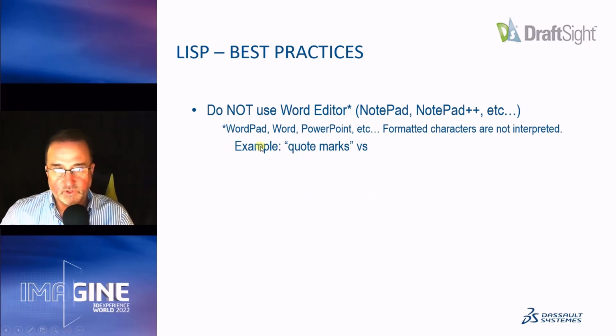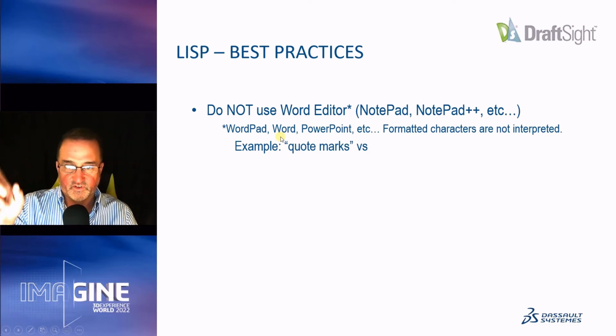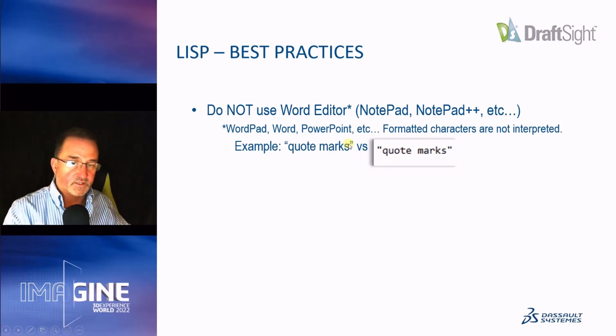For example, if you look at the way this appears on the screen, you'll notice that in PowerPoint, I have these right and left quote marks because it looks nice, but the reality is that those characters will not work inside of the Lisp routine because they're not considered strings. And so you have to use an editor. You cannot use Word or WordPad. You really need to use something like Notepad or a Notepad++ type of editor.